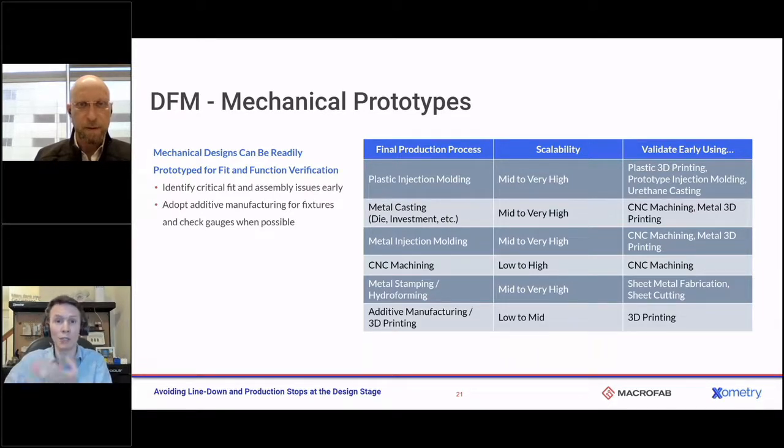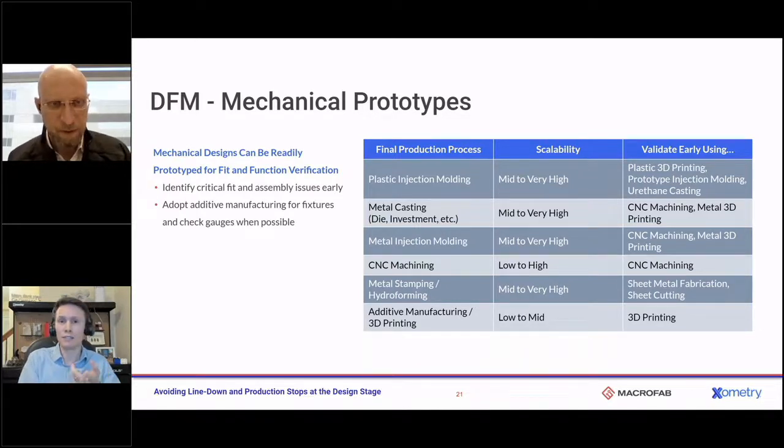We could just make an aluminum mold, a lower cost mold for lower volume production if you have a specific material. If you're more general, additive manufacturing is certainly an option, and the surface finish of AM parts has significantly improved. So it's not always a coarse, rough draft anymore. You can get some really fantastic results with that. And urethane casting is kind of like that in between, usually sub 50 units. So for these metal processes, sometimes just machining it is a very good option.